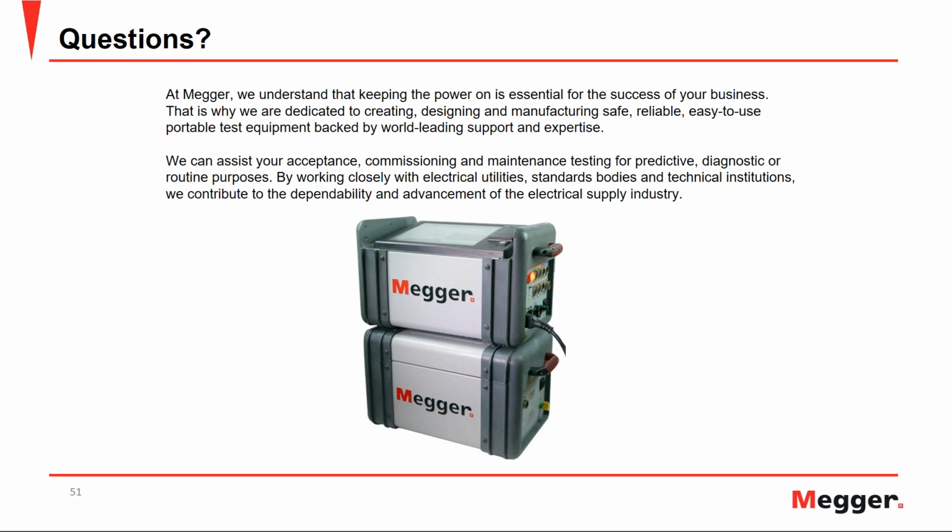A transformer that is showing high power factor values, I might test on an annual basis compared to a transformer that is showing really good power factor values. I may follow my routine preventive maintenance cycle as listed by different utilities, and every utility is different. So there is no straight answer to this. It would vary based upon the methods and practices followed by the utility.